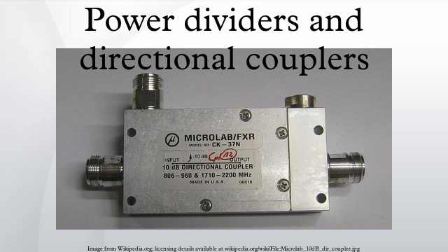Depending on the frequency range, coupling loss becomes less significant above 15 decibels coupling, where the other losses constitute the majority of the total loss. The theoretical insertion loss versus coupling for a dissipationless coupler is shown in the graph of Figure 3 and the table below.